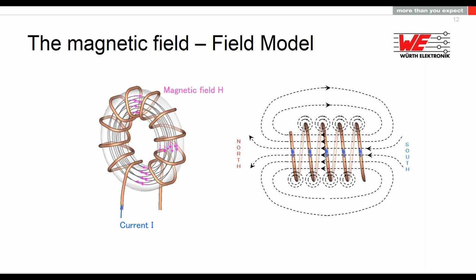In fact, with the toroidal inductor, you make a magnetic short circuit. You put the north pole together with the south pole. In this case, in the toroidal inductor, you catch the whole magnetic field inside. It cannot escape anymore. Now, this is good because it cannot make any more magnetic fields, but it saturates very fast. So actually the manufacturers are playing with these air gaps, because the air gap is something where you can store the energy and you can avoid very fast saturation.